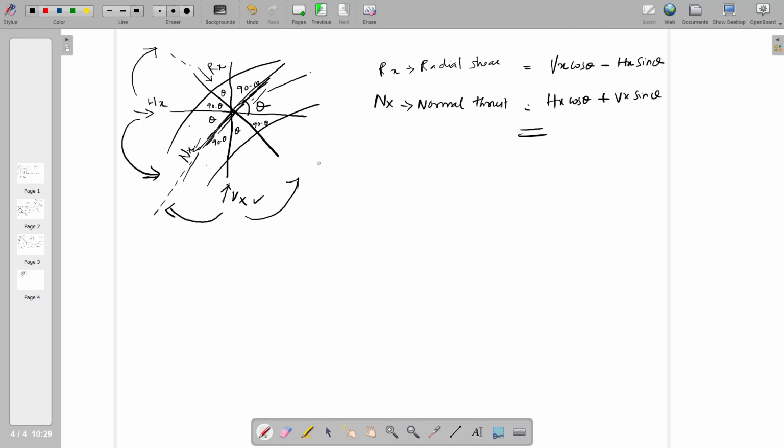Now we are going to have a simple problem proving the bending moment along the arch profile is zero for the loading condition of UDL, because normally a simply supported beam with the UDL w Newton per meter will have the bending moment as wL square by 8. So this profile is the parabolic profile.